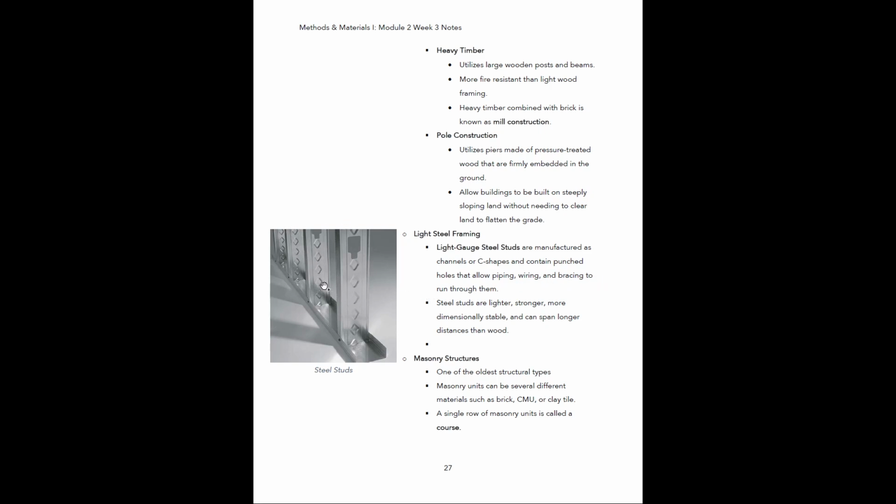So if you look at this example of a steel stud here, we have our studs, and then these are basically resting in a C-channel sole plate, and they're screwed right there with a fastener to hold them to that bottom plate. And then right here are these holes that they have punched in them. And these holes are where you run your electrical or your plumbing lines, okay? So you'll run that horizontally from one stud all the way through the next.